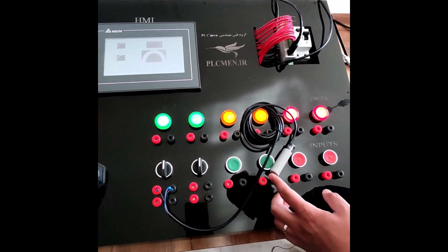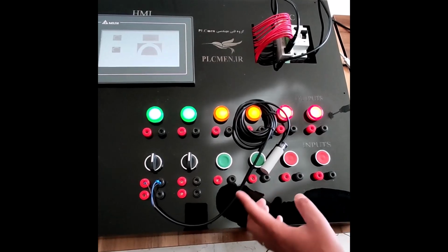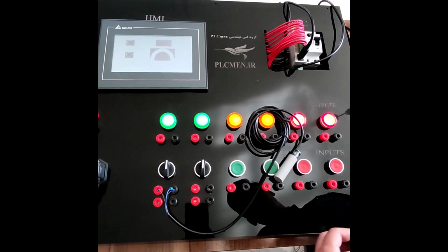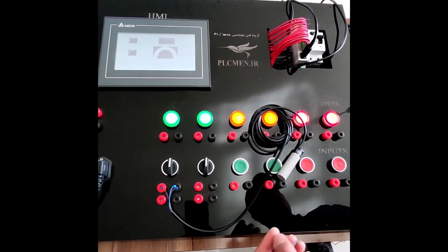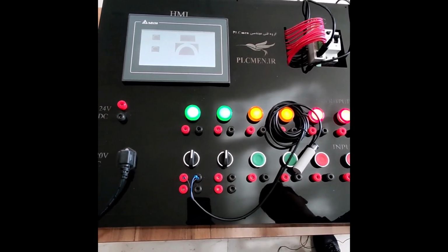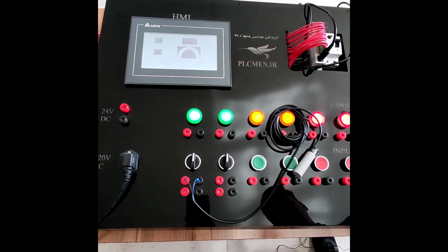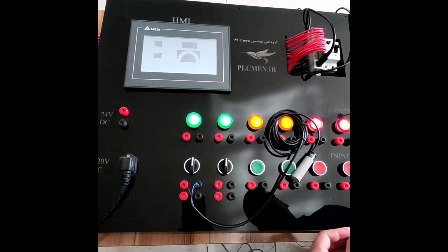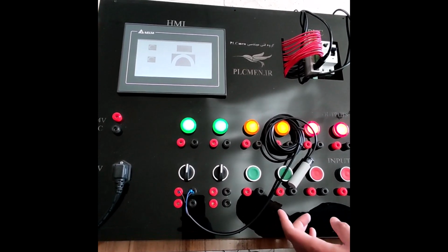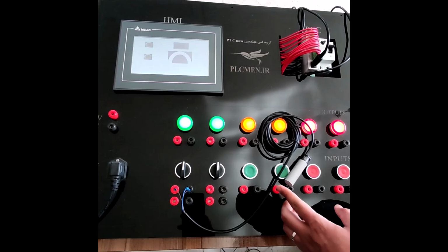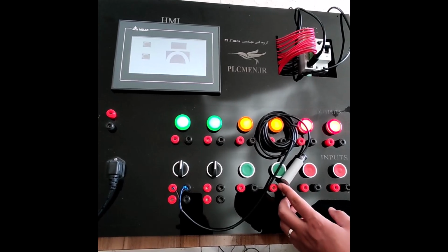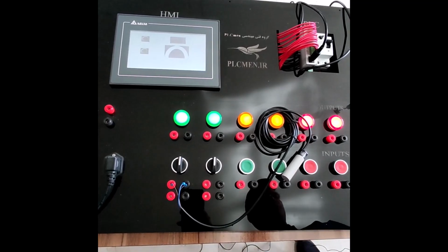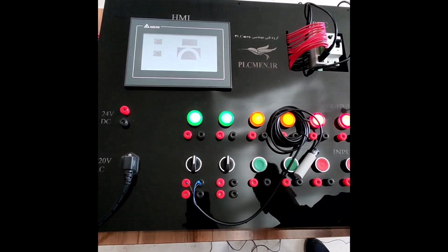We can change the PLC program and count the number when the hand moves away from the front of the sensor. That is, when the whole product passes in front of the sensor, count one number. We write a program using PLC commands inside the software, and the program uses the rising pulse and falling pulse commands, and it is a very simple program.